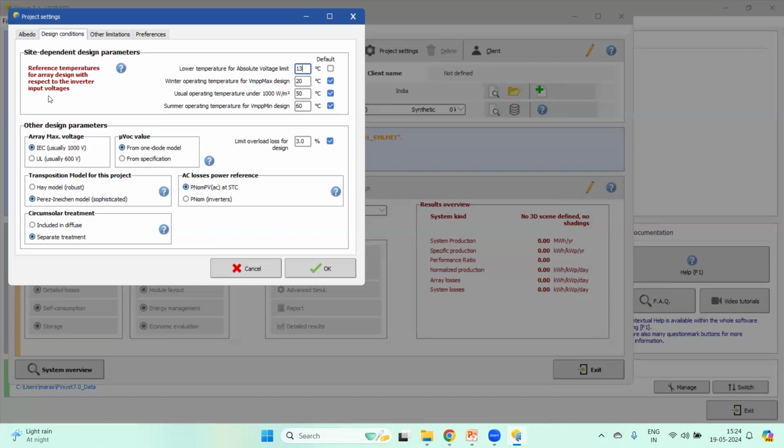For that we also have to see that the module voltage will change with temperature. We have seen the effect of ambient temperature on voltage. In the manufacturer's module data sheet, they give, for every degree temperature rise, what the voltage drop for the module will be.